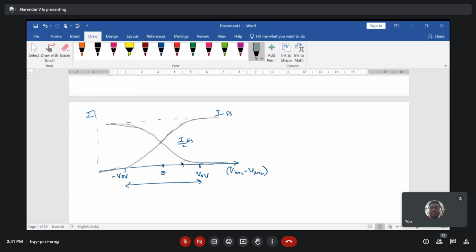Now what you can notice from this is the variation of the current with respect to change in the voltage. So this is the x-axis, which is change in the voltage, and this is the current. So change in the current by voltage is referred to as your gm, transconductance. Gm we already defined as del id by del vgs. This slope will define the transconductance of your amplifier. And we are well aware that if transconductance is enhanced, then differential amplifier gain is going to be enhanced, right?